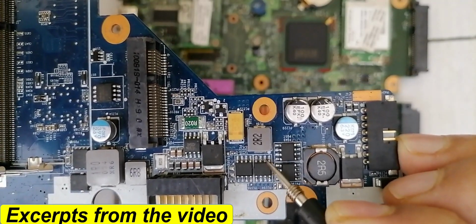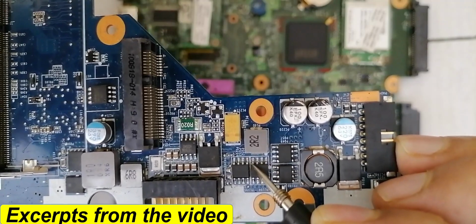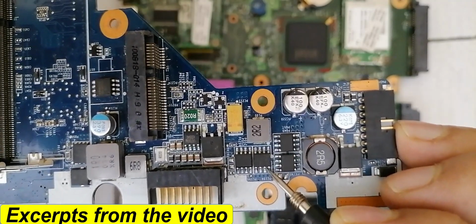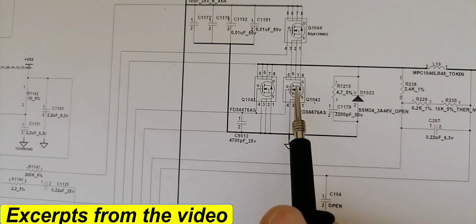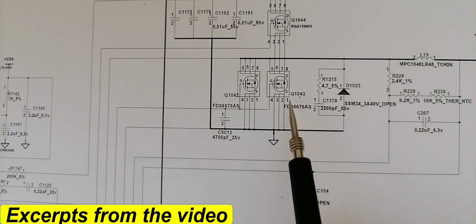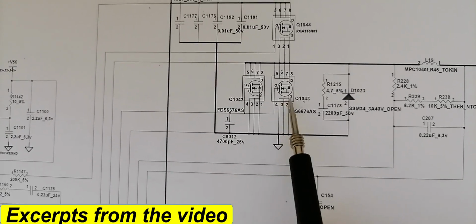So these 3 pins are source. The pin number 4 is gate, and the 4 other pins are drain. As you can see here in the schematic, do you see here we have pin number 1, 2 and 3? So these 3 pins are connected together.